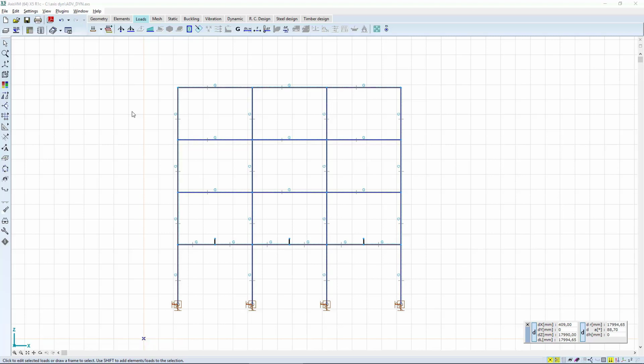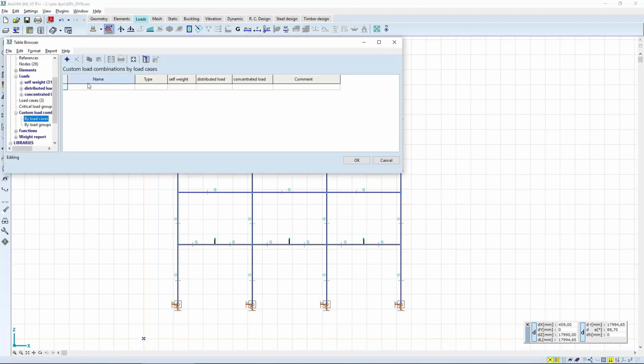In the case of a seismic sine wave excitation with a shock load, we will consider only the horizontal mass component because the applied dynamic load contains only horizontal components. In the case of the machine-induced vibration, the vertical component must also be taken into account. The same compilation of static loads will be applied for each dynamic load, but due to the considered mass components, the vibration analysis will be performed on different combinations.